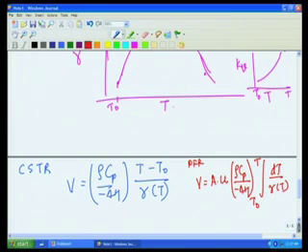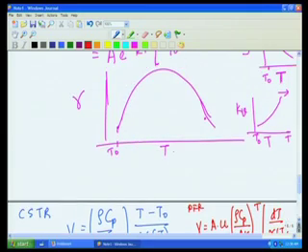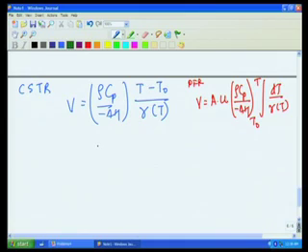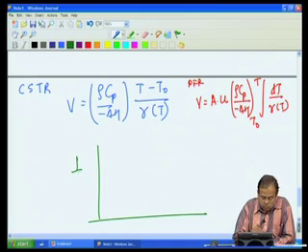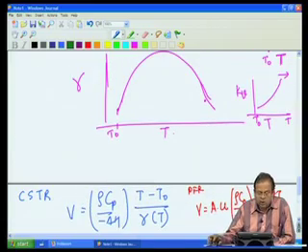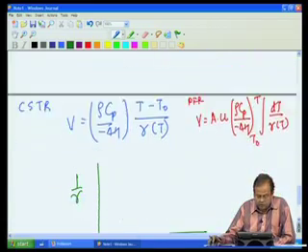So, our usual method of comparing the two reactors, plug flow and CSTR, can conveniently be used for this case as well. What is that usual way? We see that it is determined by 1 over R. So, from this R versus temperature, that is rate versus temperature, let us construct 1 over R versus temperature. It will be an inverted figure of this R versus temperature.